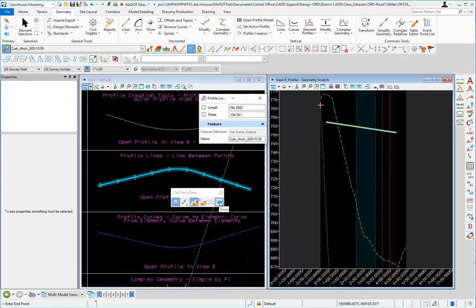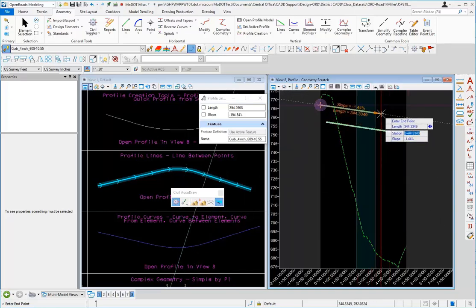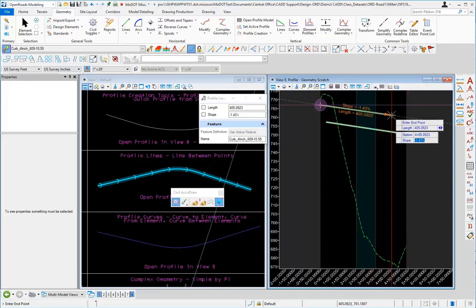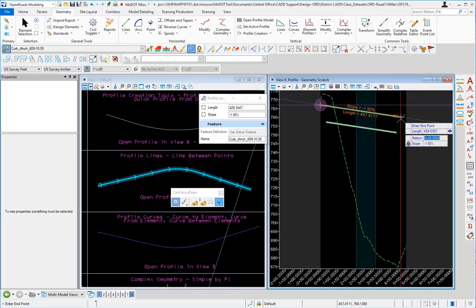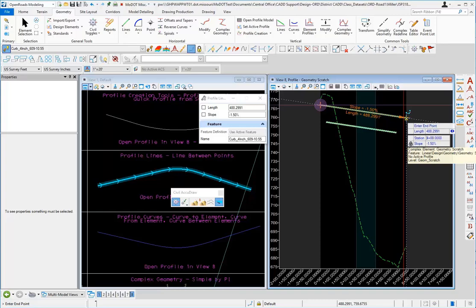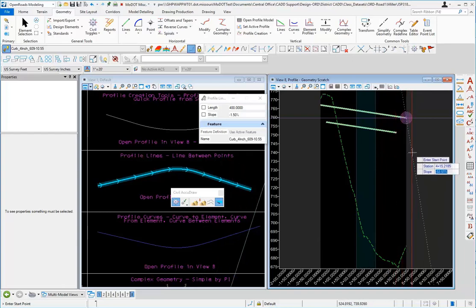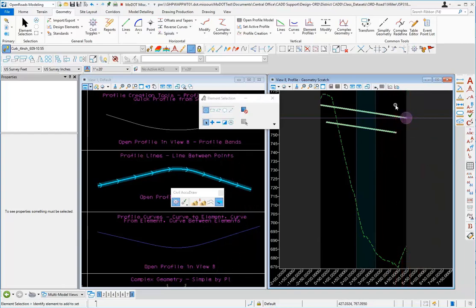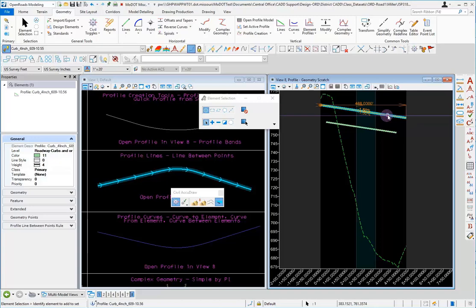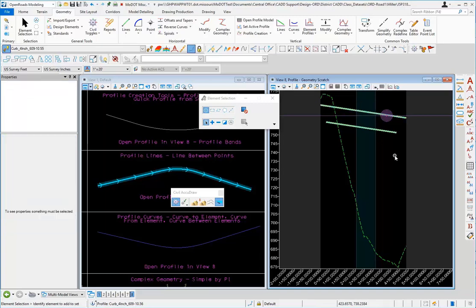So I'm going to go back into Civil Accudraw and switch it to slope. Now my slope, all I have to do is come out in the window and tab, and I can key in a slope of negative 1.5 and hit enter. That's going to lock that line in that location. Now I can give it a station here as well. 4 + 88, hit enter, and now I've locked it in. Then just left click to accept it, and I've got a line that's drawn out there at a certain distance and slope at a starting elevation. I can still modify those dimensions if I need to at any point.